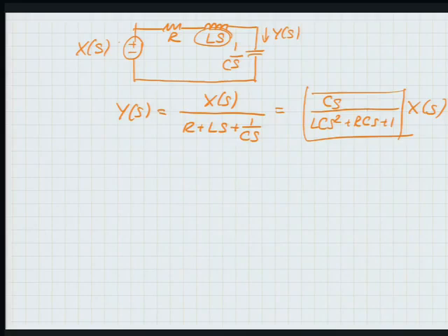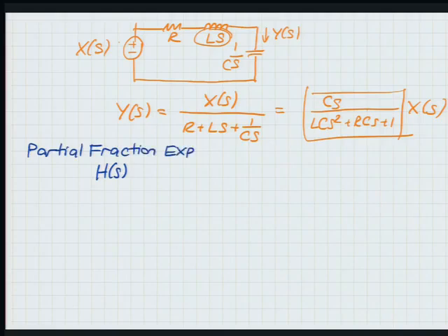All right. So anyhow, let's talk about what poles mean. I mean, the fact that I have a pole somewhere, what should I expect from that system, right? So remember our trick last time. We would take an H of S, a polynomial by polynomial, rational, right? And then we do a partial fraction expansion. The whole idea in partial fraction expansion is to break up H into a sum of first order terms if possible. And if that's not possible, if you have repeated poles, then you may need second and third order powers. PFE.